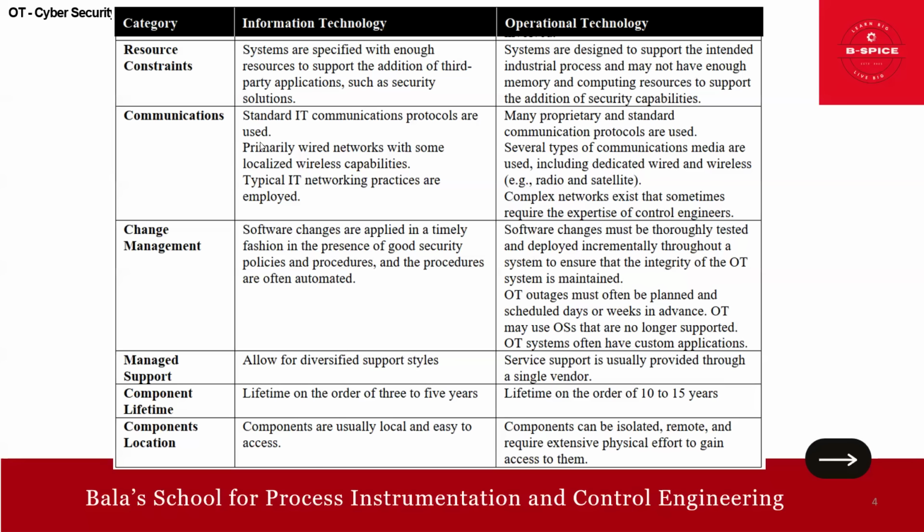Then communication. Standard IT communication protocols are used, right? Here in OT, we have many proprietary and standard communication protocols. In IT, it's primarily a wired network with some localized wireless capability, whereas in OT, several types of communication media are used, including dedicated wire and wireless, radio, satellite, all these. Typical IT networking practices are followed globally. But in OT, a complex network exists that sometimes requires the expertise of control engineers, right?